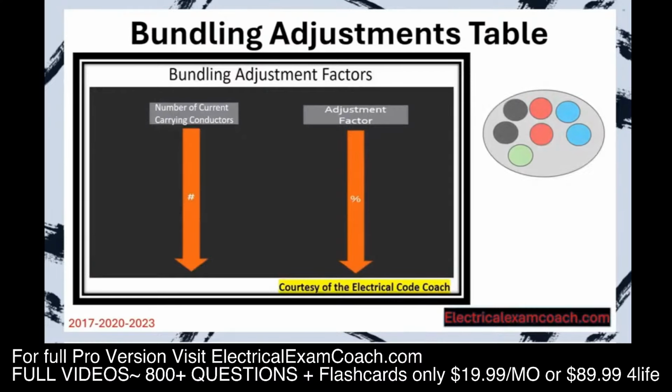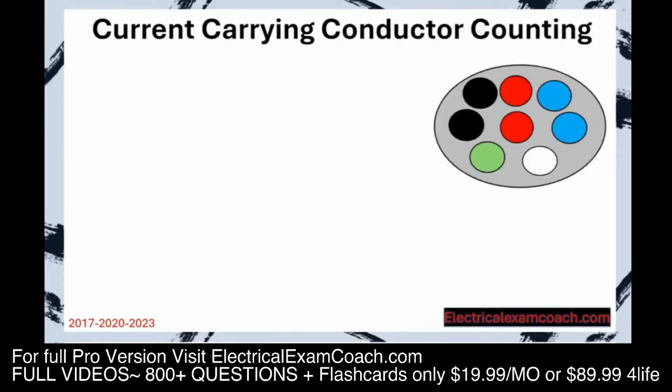Up until this point, we've had all hot conductors inside of our conduit. But what happens if we add in a neutral? Is it considered a current carrying conductor? What about grounding conductors? Are they considered current carrying conductors? Well, let's learn how to count conductors now. Now let's learn about current carrying conductor counting, because we're only going to be counting the current carrying conductors.